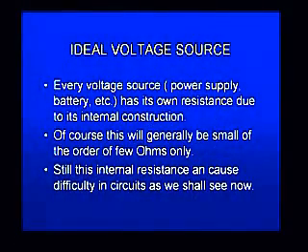So any power supply for that matter will have an internal resistance. The resistance in general will be kept very small, but there is a finite resistance associated with every voltage source, be it a battery or a power supply. This internal resistance will produce a lot of problems unless one takes note of it, because whenever I apply the voltage source to a network of resistors, there will be a current drawn, and depending upon the amount of current being drawn, there will be a voltage drop in the internal resistance of the source, and therefore the amount of voltage available for the external circuit will decrease.